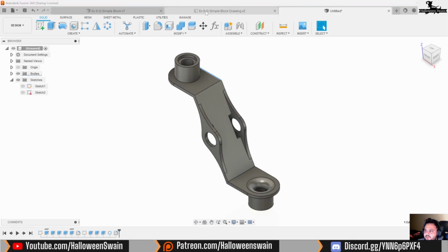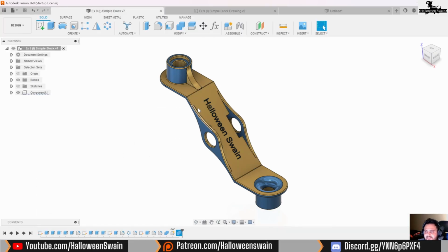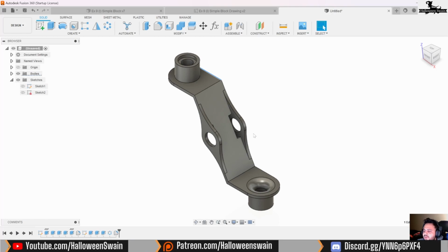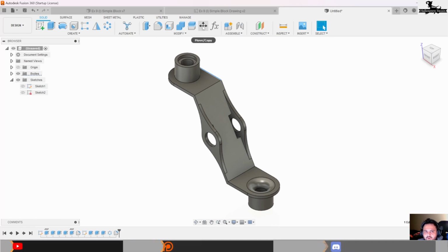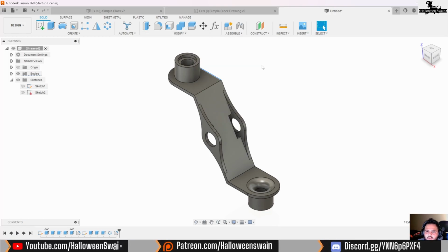This one is a new body, but for this one, when I was creating the design, I created every part as a new body so that if there are any changes, I can make them easier. And at the end I just made the body one. So as you can see, this is the same part now. This is a simple part, but I can say you should try to use that move command a lot, because we are going to use this command a lot in the export one, because there are so many parts and we are going to start assembling them as well. So just be familiar with this move command. This is one of the simple exercises, beginner to intermediate level.